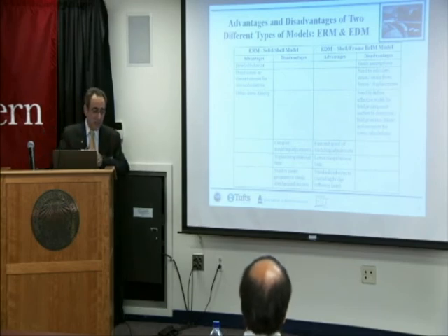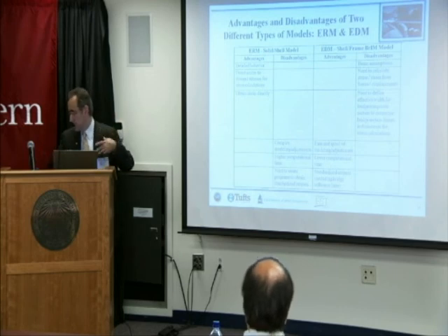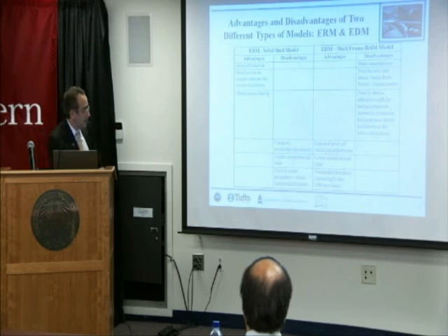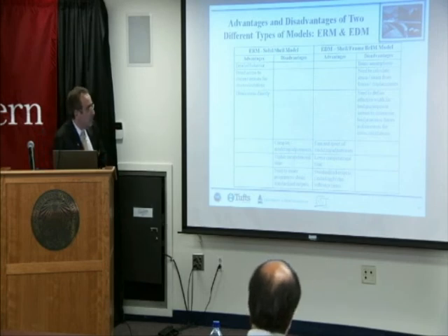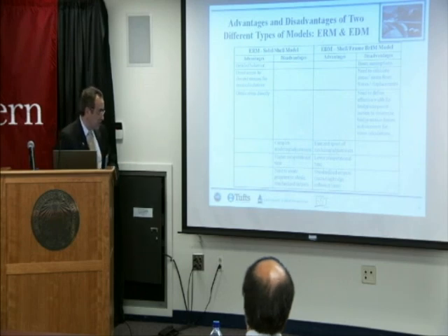So we didn't have to make any assumptions about what part of the deck was fully participating in the composite action between the steel girder and the deck. With the BrIM model, we use beam assumptions, then we have to calculate the stresses and strains based on the section of the girder and the deck, and need to define effective width. The detailed model is more complex, whereas BrIM is easier to use and easier to make changes.